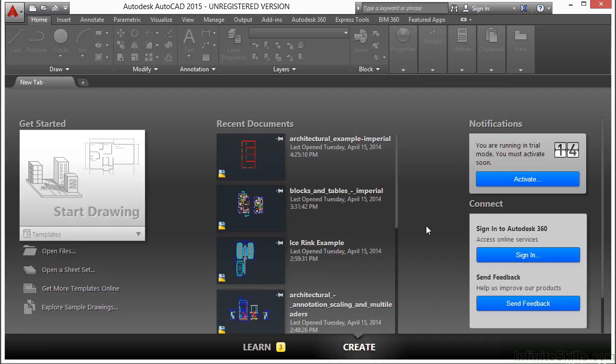Perhaps one of the biggest issues when creating drawings on a computer is making sure that they turn out the way you want them to on paper. This is where good layer management and use comes in. The purpose of layers is to organize the data in your file so you can work with it and so that it has a correct visual display on paper, not just the screen.